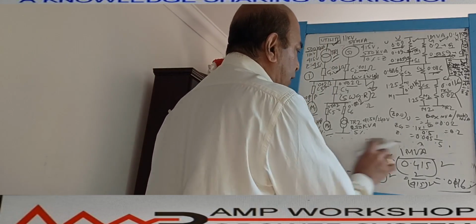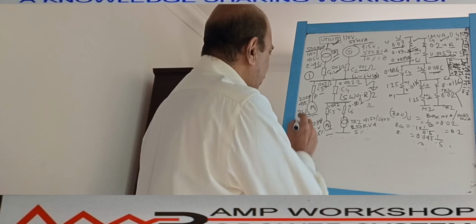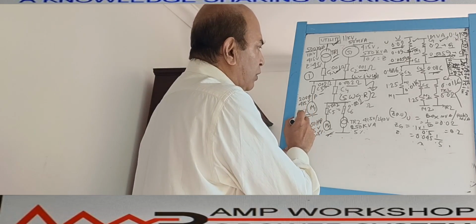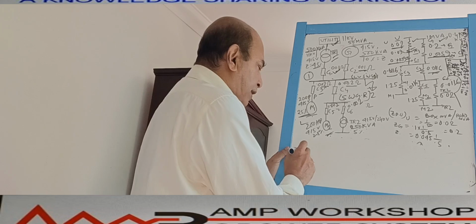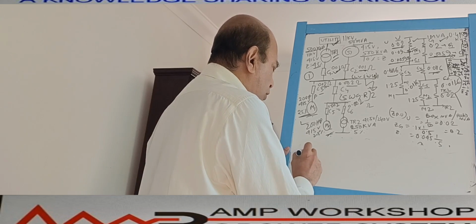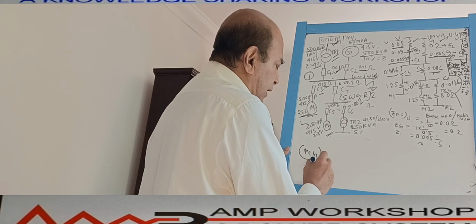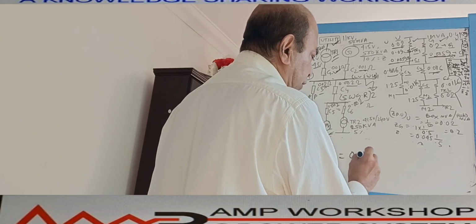So we are getting this value. Next, we have to calculate this. This motor and this motor are the same. So how much is this motor? This motor has 25% impedance. So 25% means what is the impedance per unit value? For motor M1 based on the base MVA, per unit equals how much? 25% means 0.25 per unit, right?